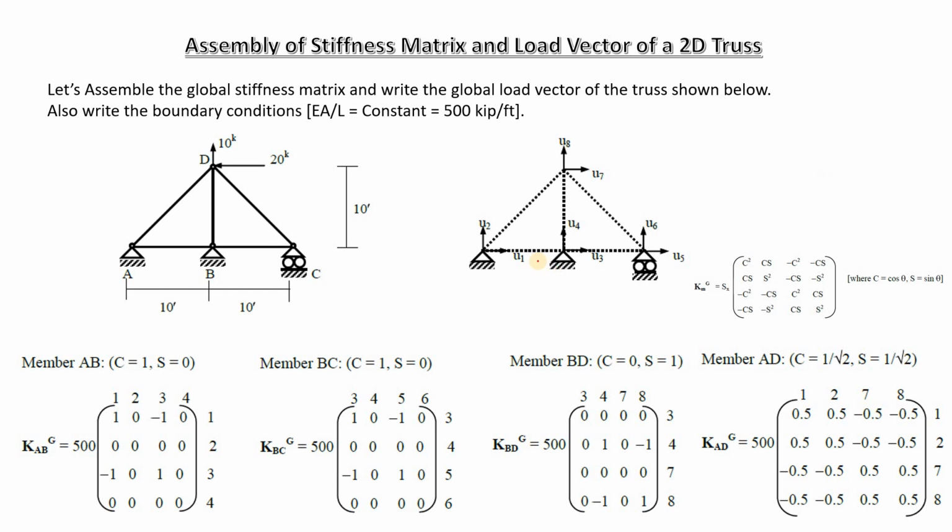Right after that, we're going to see where the displacements will occur. The displacements are going to occur at the joints. So we have 4 joints, so there are going to be 4 multiplied by 2, 8 displacements. So these are the displacements here in this figure. They are named accordingly. Okay, so A is the first joint, that is why the horizontal displacement is being called U1, the vertical displacement is being U2, second point being the B point, it is U3, U4, and then the third point being the C point, U5, U6, and the fourth point being the D point, we have U7 and U8.